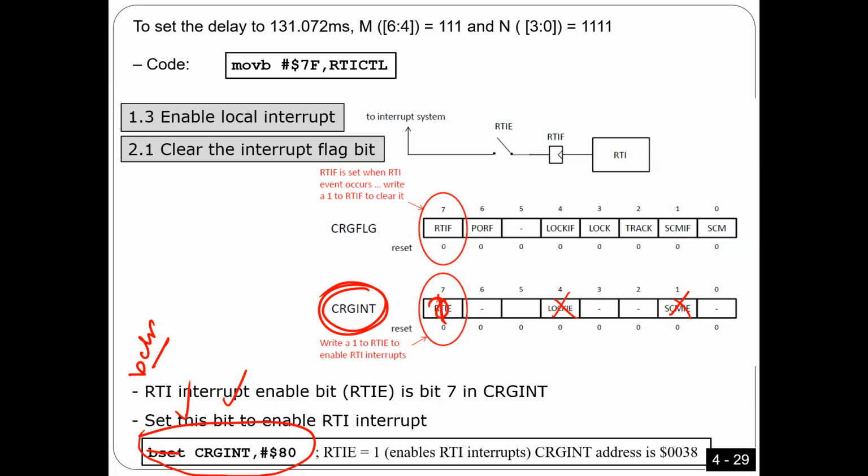So if RTI is used to make a buzzer, to make an alarm like this one, as long as it's enabled, you enable the task, you enable the alarm. Same thing for flashing. So that's what you should understand. When you disable RTI, it means you are not going to call the subroutine. That means the task RTI is doing, you are not going to do it. So there is no flashing.